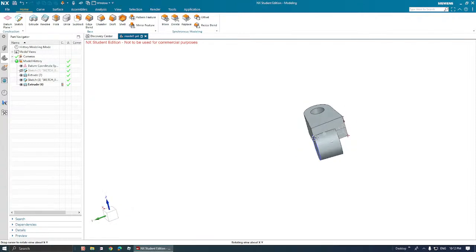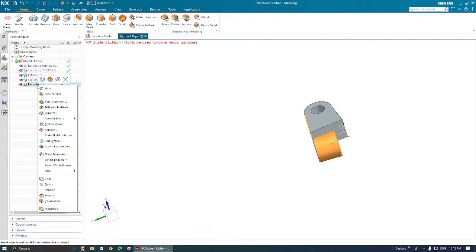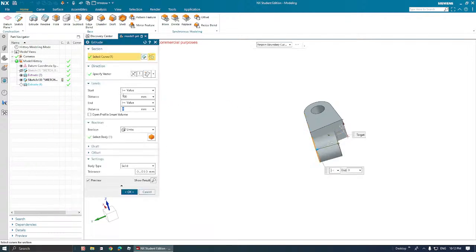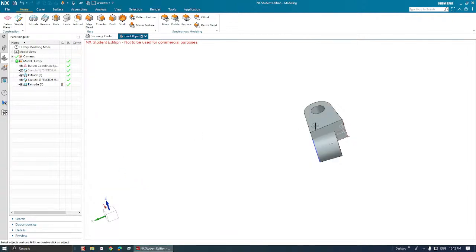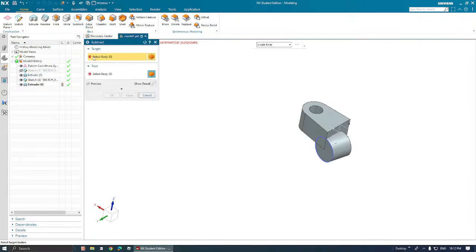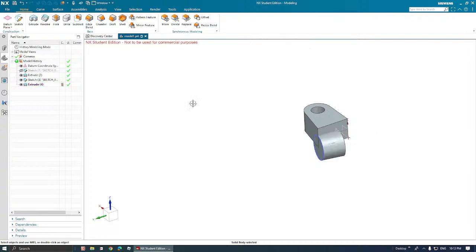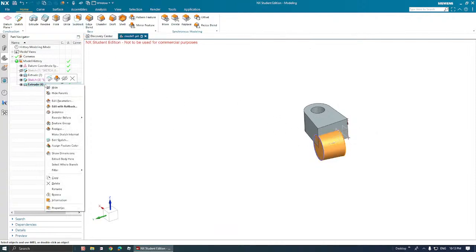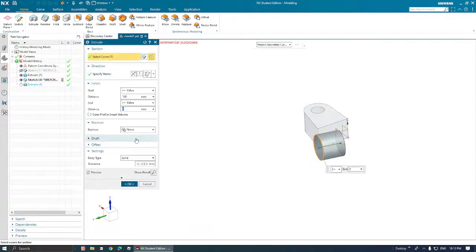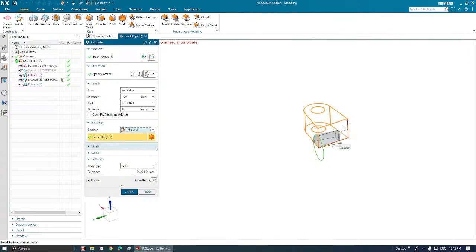That's interesting. Right, so this is now highlighted, and if I choose none, you can see these are separate objects. I guess we can just go ahead and apply this with target object and tool. So we can subtract it before or later, whenever we want. We can do it from here, or from the option right here. Intersect is going to create this particular part.